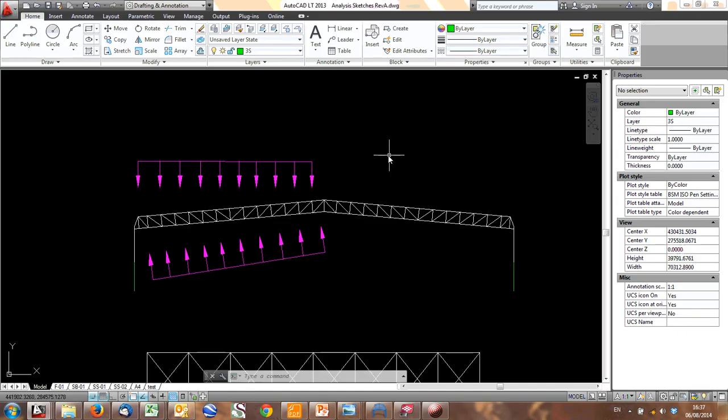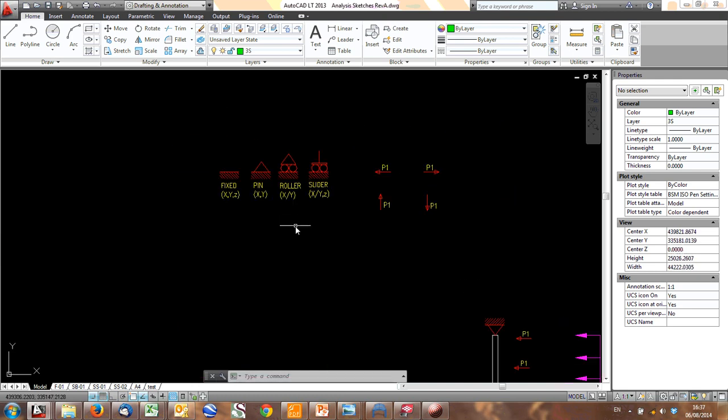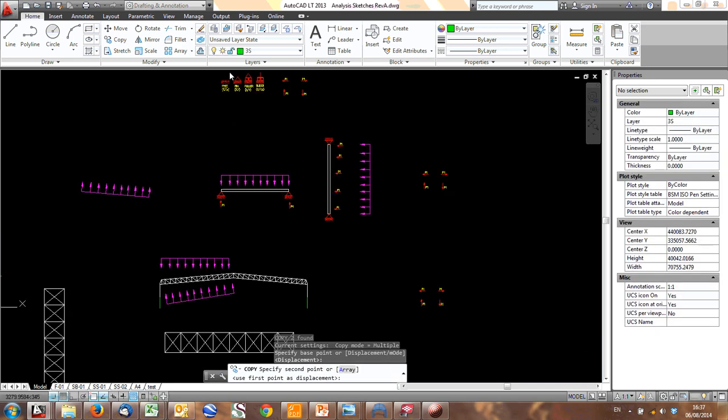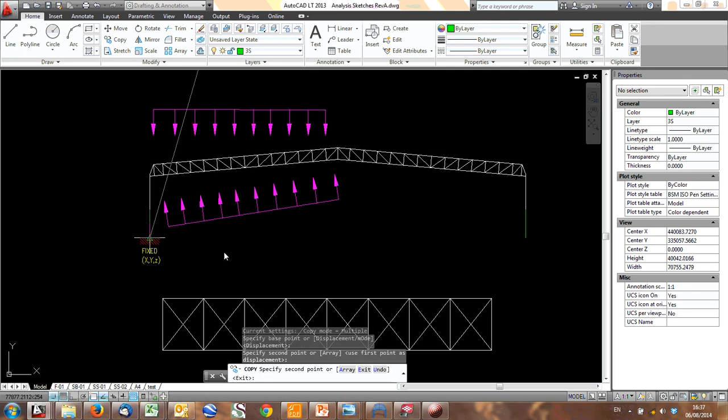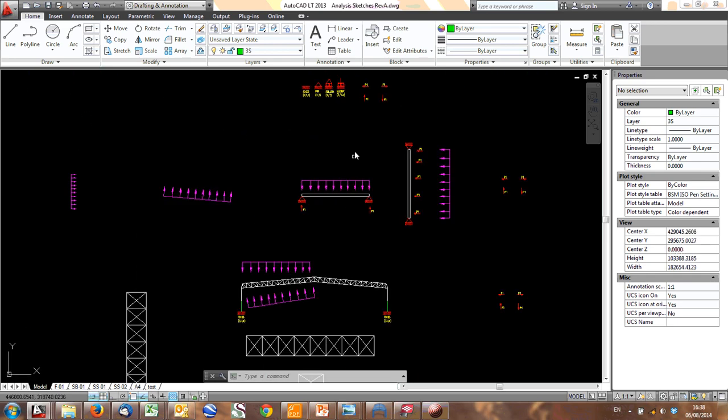So, if you're going to add a support, you can add various things. First, we're going to have to add some fixities. At the bottom of our concrete columns, we've got a fixity, so we've got a fixed connection there. But how do we model that? If there's load coming down there and it sits on the girder, remember we looked at the girder just now, this can't deflect. The girder is normally very much stiffer, so we can approximate that girder by putting in a support.